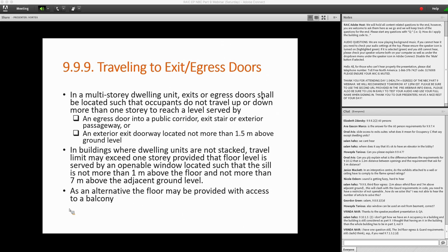So typically, public corridors are required to be 45-minute fire resistance rated, and separated from the remainder of the story. But in a sprinklered floor area, the portion of a public corridor between this assembly occupancy, which is not a major occupancy under Part 9, and the public corridor is actually permitted to be just a fire separation without a fire resistance rating.